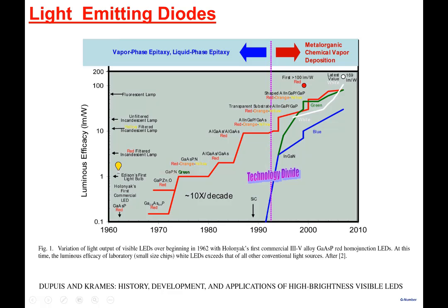And people could also see that there did not seem to be any inherent limitation from physics that you could not get beyond, let's say, 200 lumens per watt in an LED. So the path was clear that as you understand and develop better materials and better structures, we could go beyond 100, between 100 and 200 lumens per watt. So it was clear that we could make very, very efficient light sources.